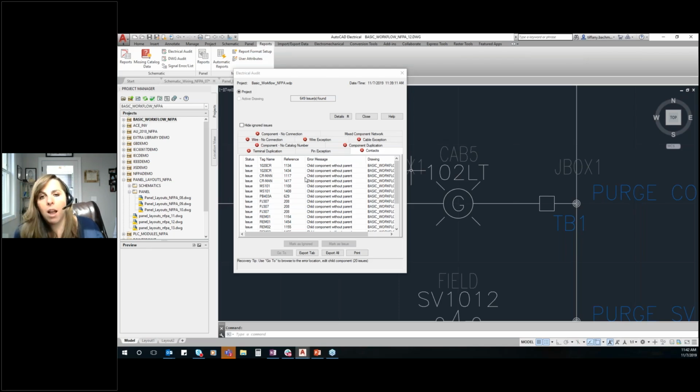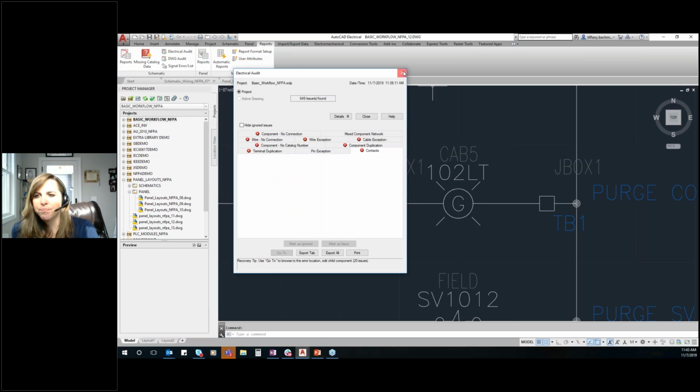In another dialog box, you'll see it references orphan children. It's a situation where they're not getting any of the information that they need to actually produce what's needed within the project. So those three columns are really, really important for you to do error checks on before you finish any project, in my opinion. So that is the auditing tools. There's obviously more on here. I'm not going to spend forever on them, but I just wanted you to see the top three and the reasons why we would look at those things.